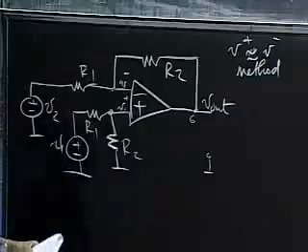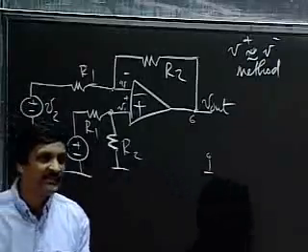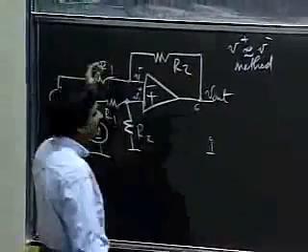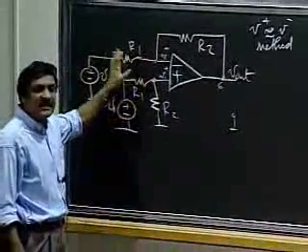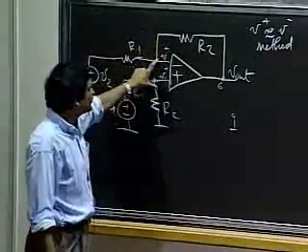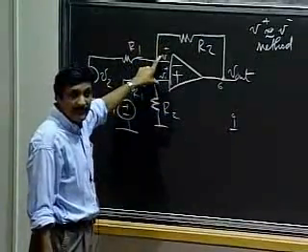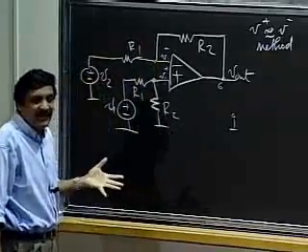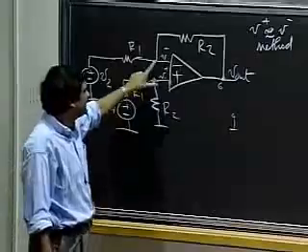and tend to make these two equal. So what we can do, being rather tricky here, is say, look, if we know for a fact that under negative feedback the op amp is going to engineer these two node voltages to be more or less equal, then why don't I just use that fact to begin with and analyze my circuit assuming that is true?